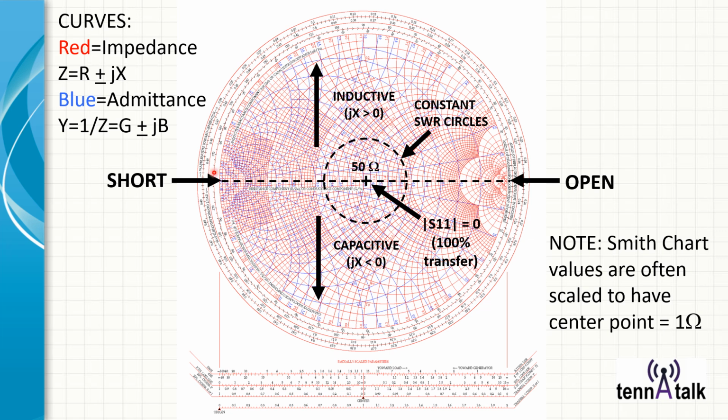So first thing to notice is this equator is the pure resistance. Impedances are given by R, the resistance, plus a reactance value, that's plus or minus. If the coordinate that the antenna is sitting at gives you a dot at that frequency north of the equator, north of the resistance line, it's inductive. Positive reactance is inductive. Negative reactance, it's net capacitive. And this is why if it shows you something capacitive, you have to add an inductor, and vice versa.